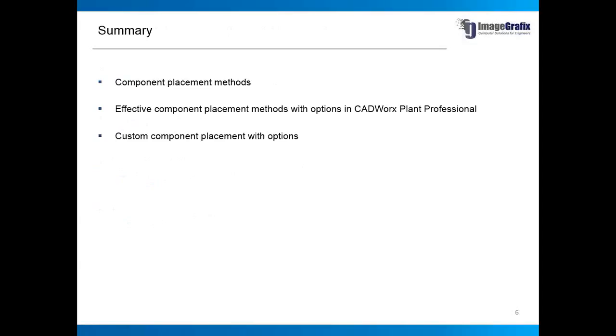And also here I have used the convert enhanced option for showing the bolts in your valves. Normally when you create a pipe, it is shown only as a solid pipe. Now if you want to show hollow pipes, if you use the convert enhanced option on your pipe component as well, then you can see your pipe as a hollow pipe. Fine. So I'm sure this will be really helpful.